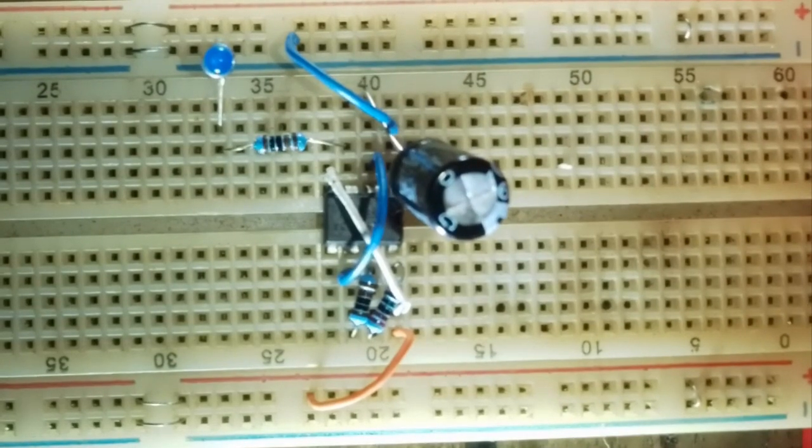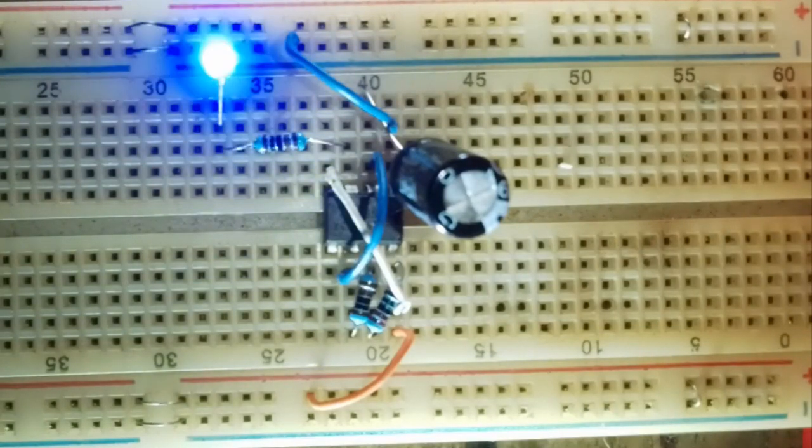Do you notice how nicely the LED flashes? That's because we get a near perfect square wave out of the 555 timer IC output pin 3. Fortunately, you have control over how fast you want the LED to flash or turn on and off. You can do that by playing with the values of C1, R2, or both. Let's see that in action.